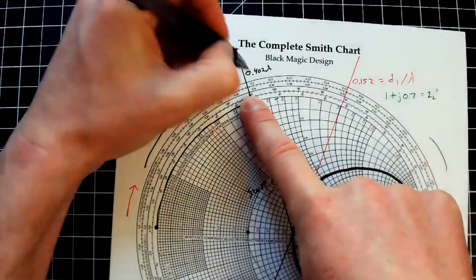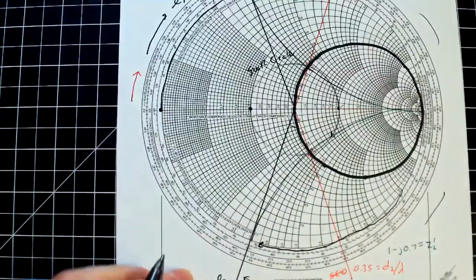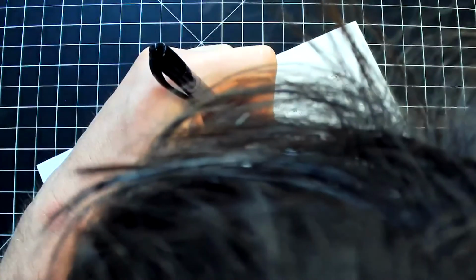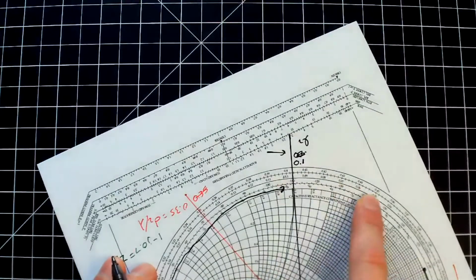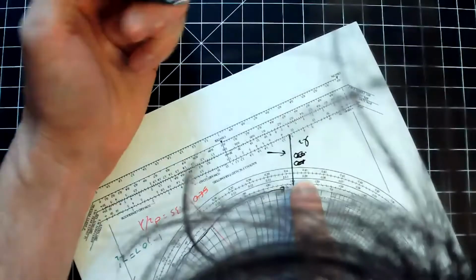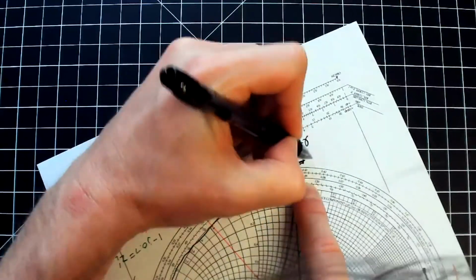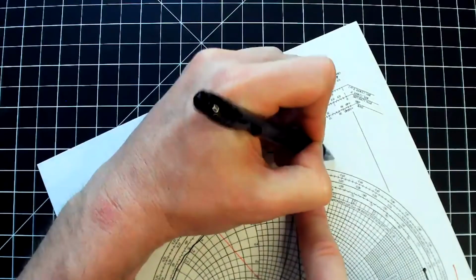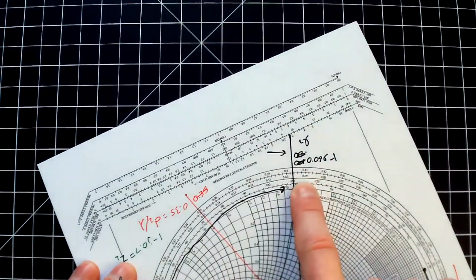And so what I'm going to get is 0.402 wavelengths. So that is my L1. Then you come all the way down here, and I get, what do we get? 0. Oh, sorry, I got to make sure I read the inner one here. So it's 0.1, except that it's decreasing that way. So it's not even that. You have to say 0.09246. So 0.096. So you have to read the inner wavelength number there, not the outer, which is what I did here.